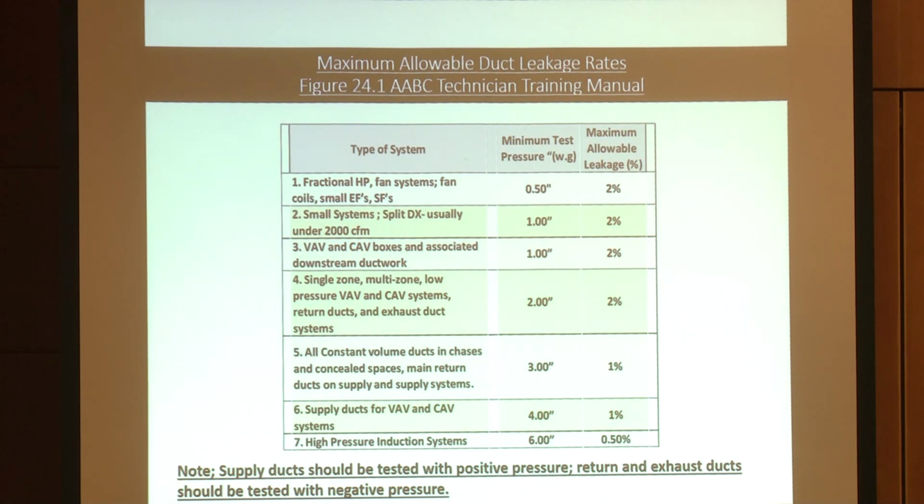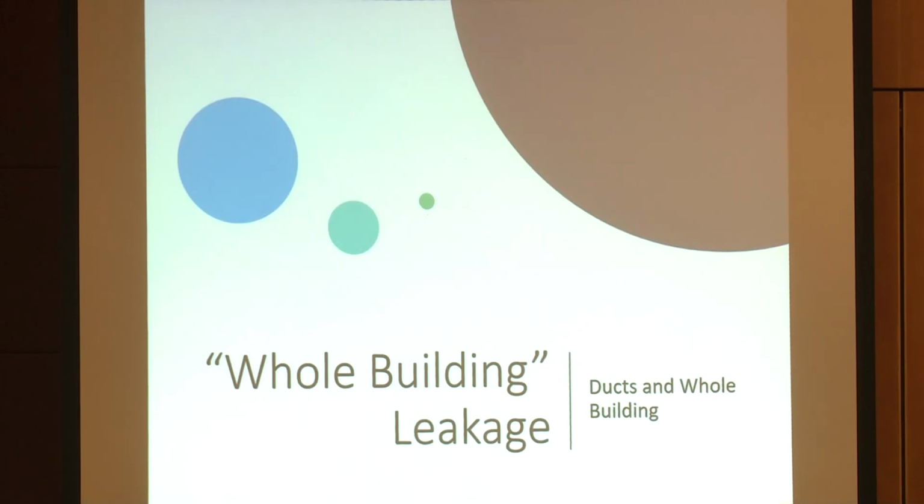So yeah, this duct testing is very, very important, because when you come down at the end of the job and that engineer specifies 1,000 CFM and you start testing the grills and you're getting 500, you know you're in trouble, and you know that nobody sealed that duct.